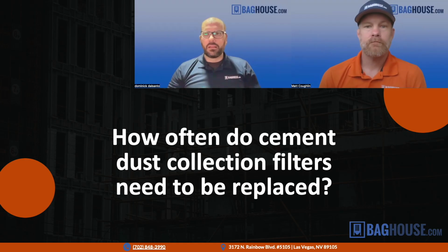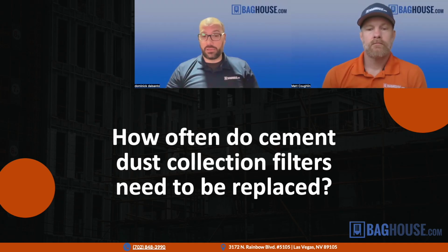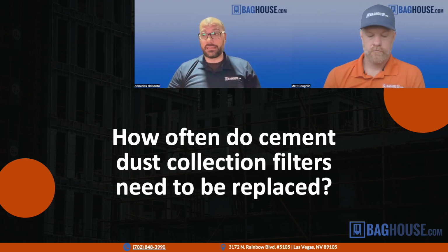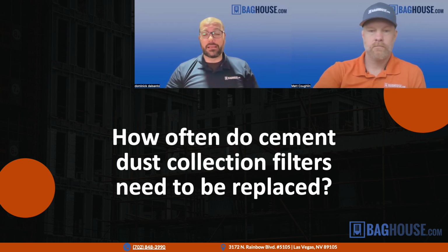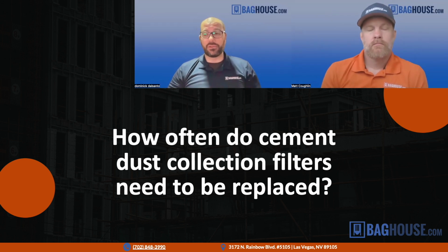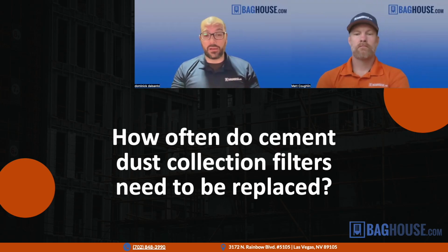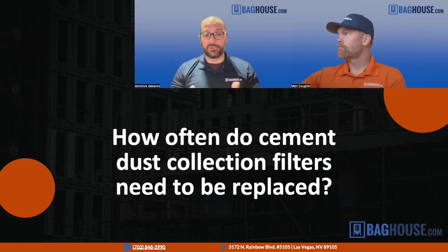Good. I would just add too, you can affect this by the way you operate your baghouse as well and how you maintain it. A big thing that impacts how long the filters last is if you over clean the filters. We talked earlier about the importance of running the baghouse on clean-on-demand, where they only pulse the filters when the differential pressure reaches a certain level and then turn off once it's cleaned down. If you just have it in timer mode, you're increasing exponentially the wear on the filters, because most of the wear that causes the filters to reach the end of their life is from pulsing the filters. It's not from the dust hitting them.